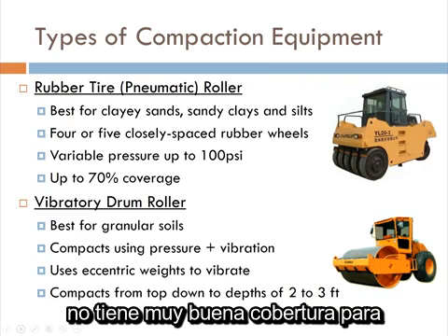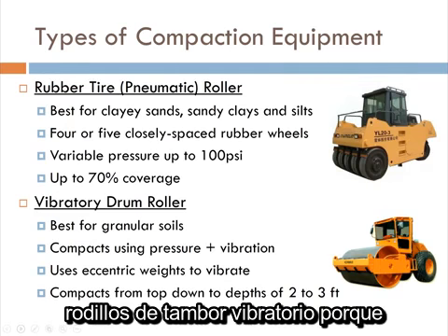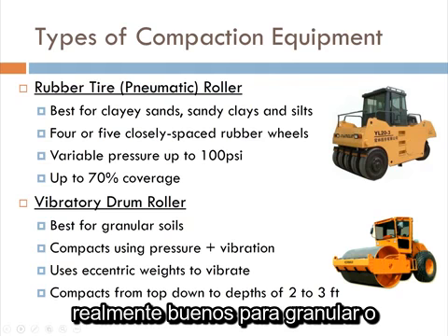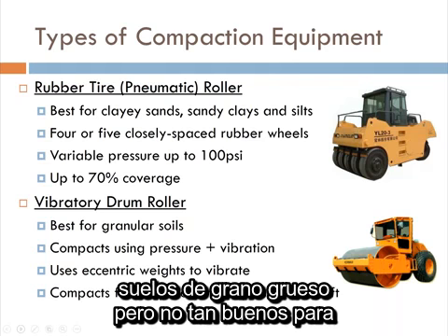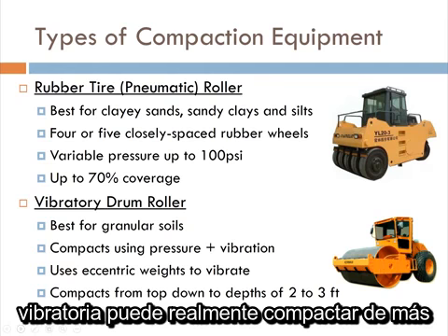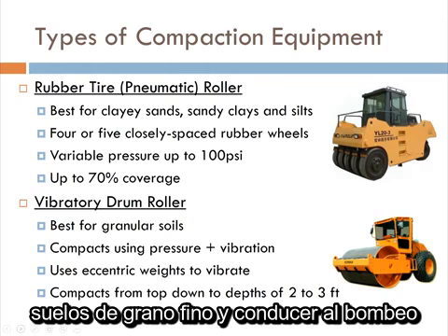but don't have very good coverage, to vibratory drum rollers, because they vibrate up and down. These are really good for granular or coarse-grained soils, but not so good for fine-grained soils. This vibratory action can actually over-compact fine-grained soils and lead to pumping.